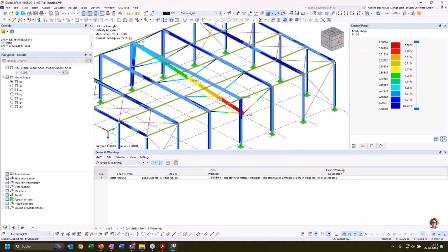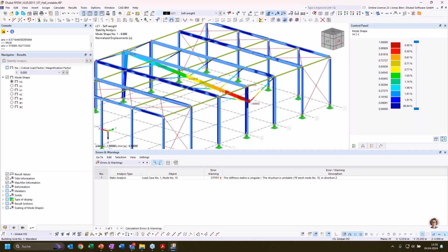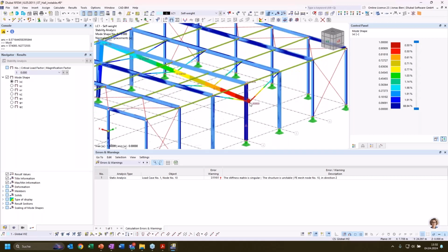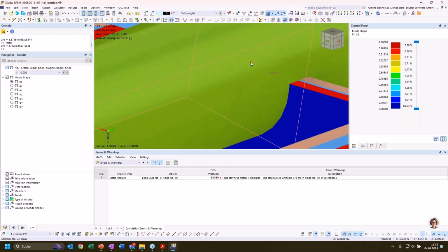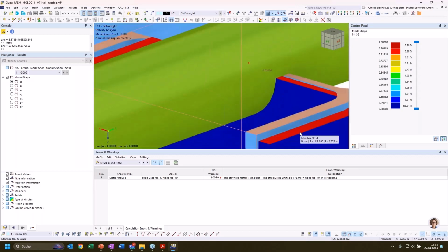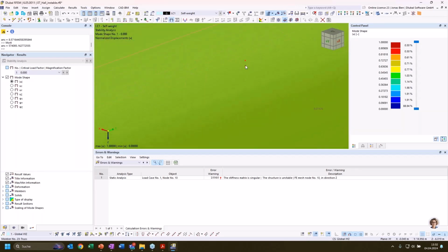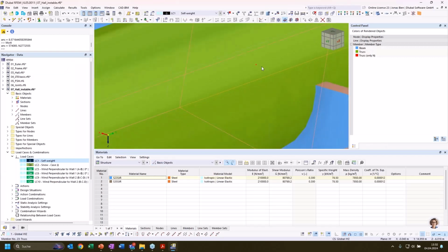And what I see now is that it seems like the girder in axis number 4 is more or less falling down. It seems like it's not connected to the beam. And when I zoom in here, I see there are 2 separate nodes, and the column is not properly connected to the girder, which could be, of course, the reason for my instability.